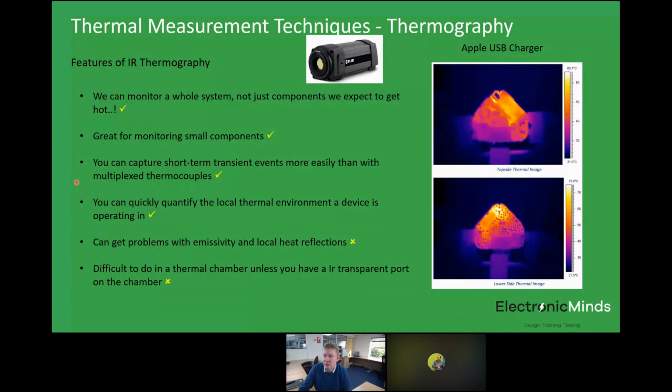So what kind of extra attention on thermal management should be paid when dealing with designs including SiC-based or GaN-based power devices? I like that question. That's a fantastic one. It alludes back to the slide at the end of my webinar. When you're working with SiC or GaN-based power devices, there are two things you'll find hard from a thermal management perspective. Firstly, the physical die that those parts are built with is smaller than for a silicon device. So even with the same amount of dissipation, you have a challenge getting the heat out, and Jose talked about this in his presentation on Tuesday. It's much harder to get the heat out of a very small die, so you have a problem cooling them.